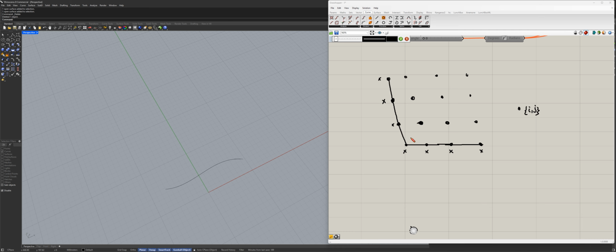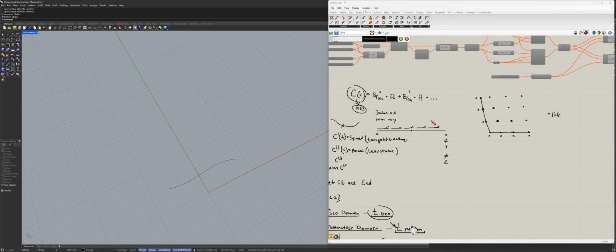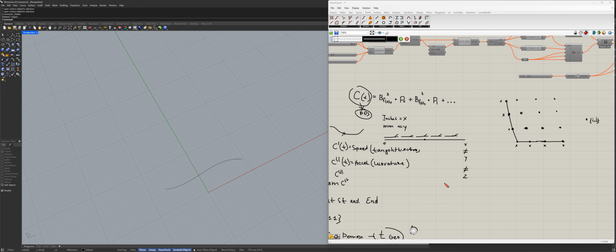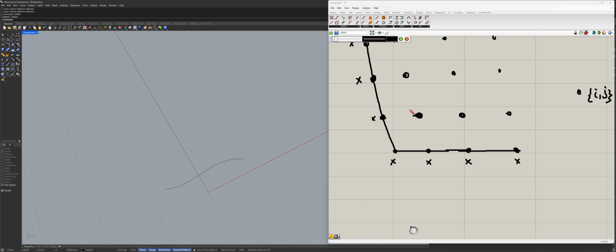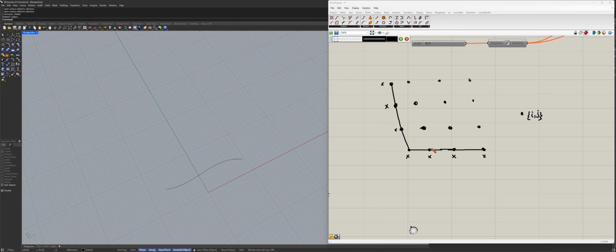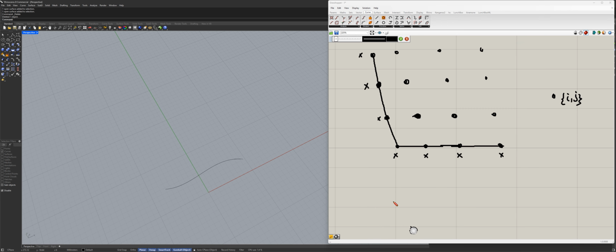How about the surface itself? Well, we have a problem here, because if you remember, to construct even a curve, you need basis functions, right? Do we have basis functions for these points? No, we don't. What we have instead are two curves which form the sides of our surface, and we have basis functions only for them. What are we going to do? Well, that's where the actual NURBS mathematics comes into play.